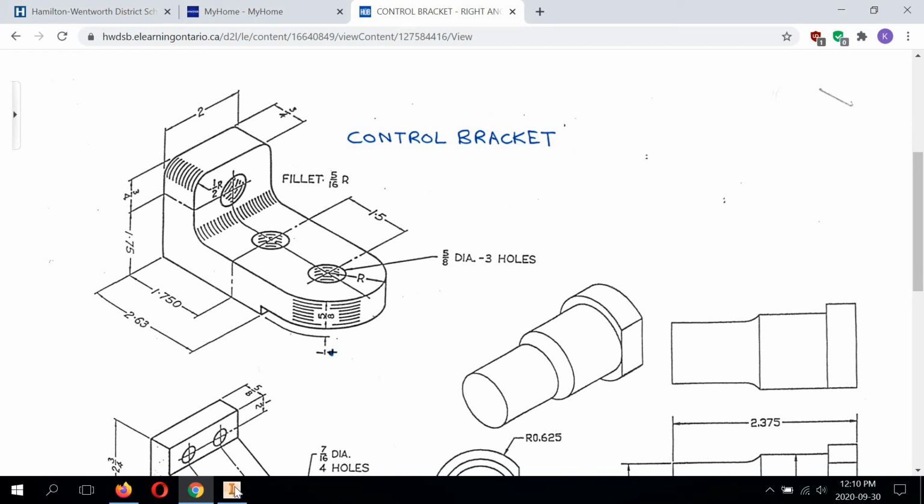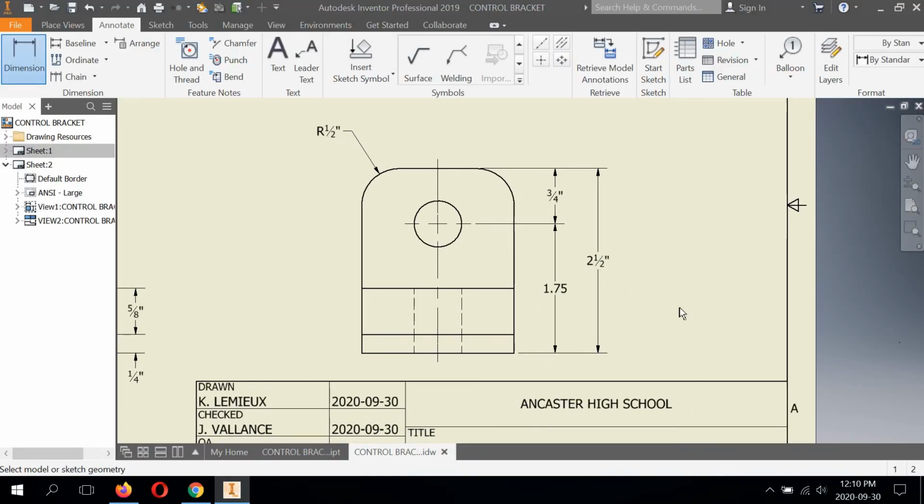These two. Now, the way you see this is incorrect. Why is this incorrect? Because this is, again, over-dimensioning. If I have a dimension here from top to bottom, and I know it's 2.5 inches, and I have this fraction, this decimal dimension, this is too much information. This is like the same thing repeated, just broken up over two sizes. So because I need to have an overall dimension, which is the height, I have to drop one of these dimensions.